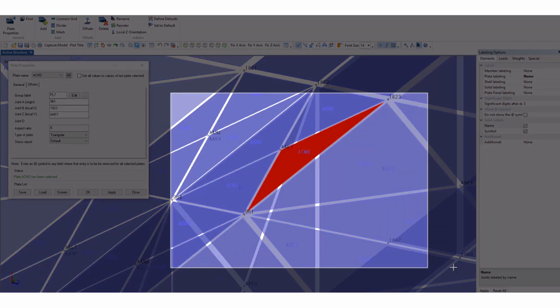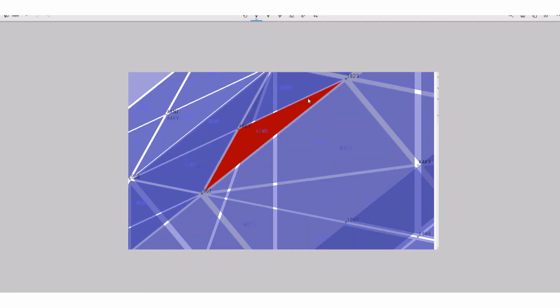If you see practically, we have an I-beam like this. This is the I-beam. On top of that you would have the floor plate like this, and the floor plate and I-beam will be welded here with a continuous fillet weld. That's why joint 961, joint 1023, is connecting both the flange plate as well as the floor plate. Here there are two joints, one for the floor plate, one for the flange plate. That's how it is modeled.